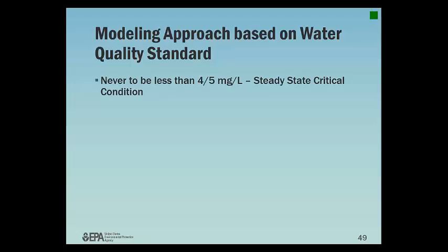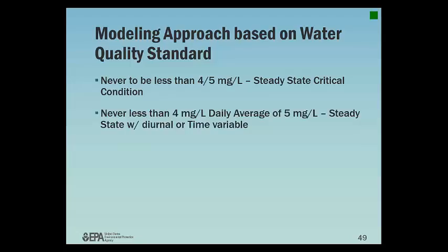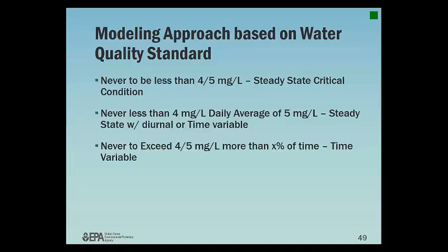You can also use time variable models in place of steady states. It's just that the solution technique is different and may have to iterate to get to that point. Never less than 4 milligrams per liter, daily average of 5. You can again use the steady state model with the critical condition, but you also have to consider the diurnal effects, change in water temperature, productivity, respiration, or you can use a time variable model.